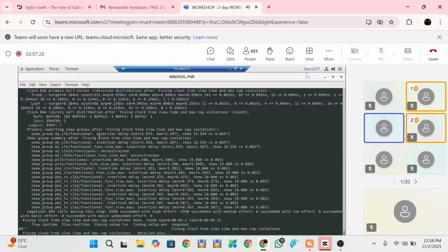I got two points, but my point is how the placement tool and routing tool will know the difference, like if a 40 nanometer node or a 7 nanometer node is being used. That is defined at the tech level. The technology is defined there, everything is defined in the tech files, and the tool uses those rules. Exactly, that is all at the tech level only.